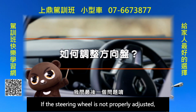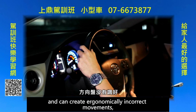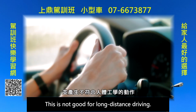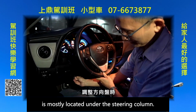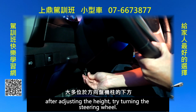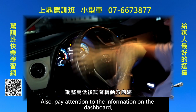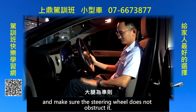If the steering wheel is not properly adjusted, it will affect our steering maneuverability and can create ergonomically incorrect movements, leading to hand, back, and shoulder soreness. This is not good for long-distance driving. When adjusting the steering wheel, the manual adjustment lever is mostly located under the steering column. If the vehicle's steering wheel supports height adjustment, after adjusting the height, try turning the steering wheel. While turning, the principle is to keep your hands from touching your thighs. Also pay attention to the information on the dashboard and make sure the steering wheel does not obstruct it.